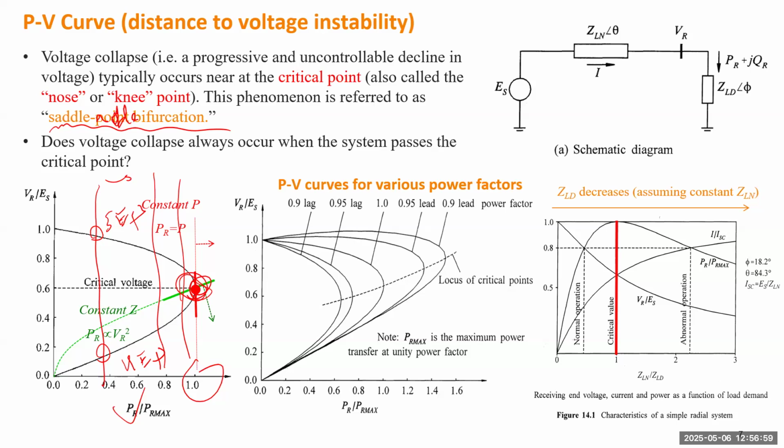At the beginning of this lecture, we'll talk about another useful tool. This PV curve is good to study how far you are from the boundary of stability for your current loading condition. And you can draw such a curve for many different power factors. If you determine the power factor for your system and you increase the load for one area or at one bus without changing the power factor, the voltage will change according to that specific PV curve.